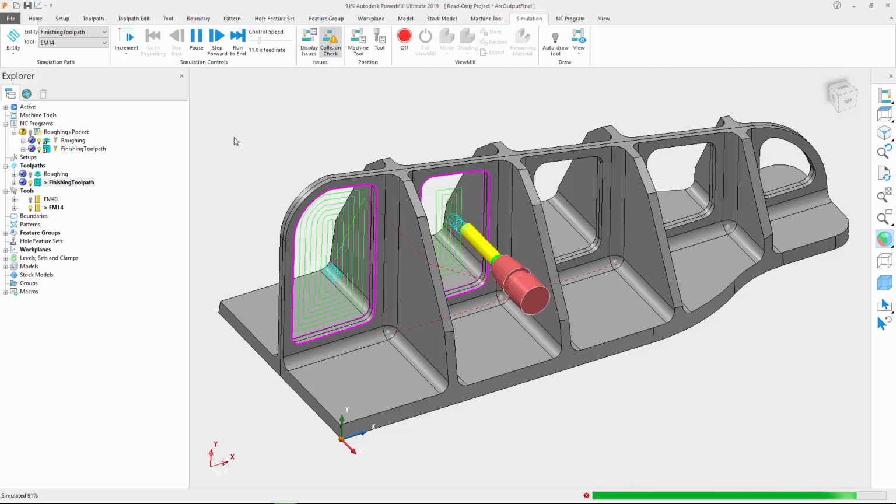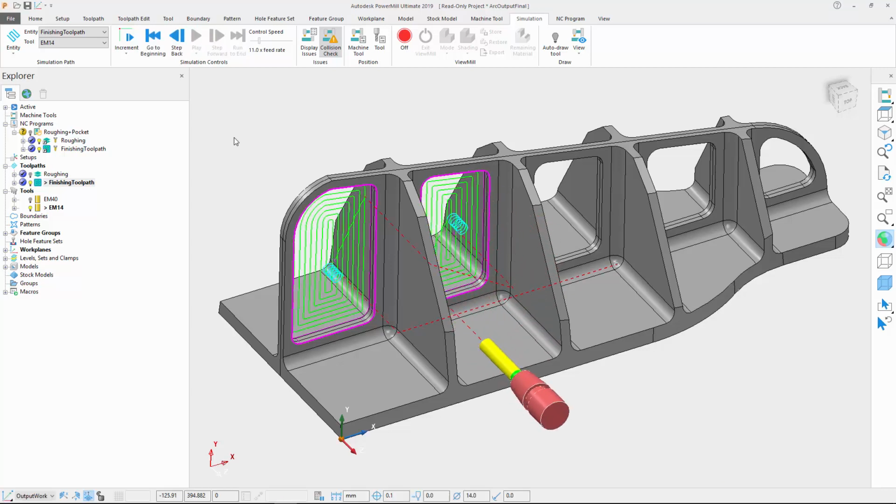Finally, this improvement will also enable the use of cutter compensation for greater flexibility on the shop floor, as we can now compensate through arcs rather than linearized segments.